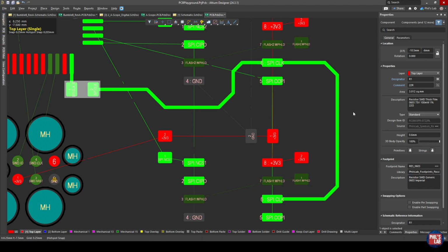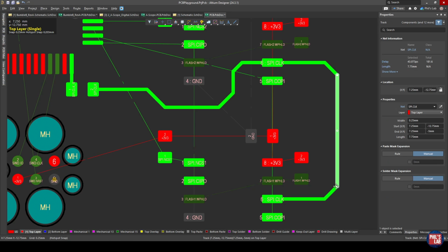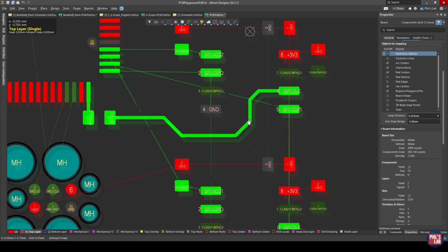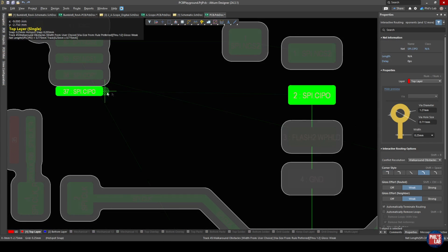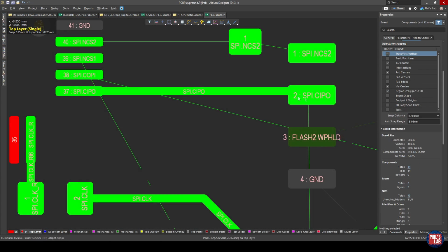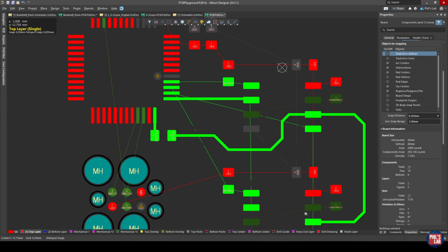And keep in mind, branch topology, especially if your devices are close together and you have short traces, can be fine as well, especially if the branches themselves are short. So you would do the same thing then for the other signals, for example, controller in, peripheral out. You can route into these pins and then through to the other devices as well. You might have to use vias to jump layers and so on.